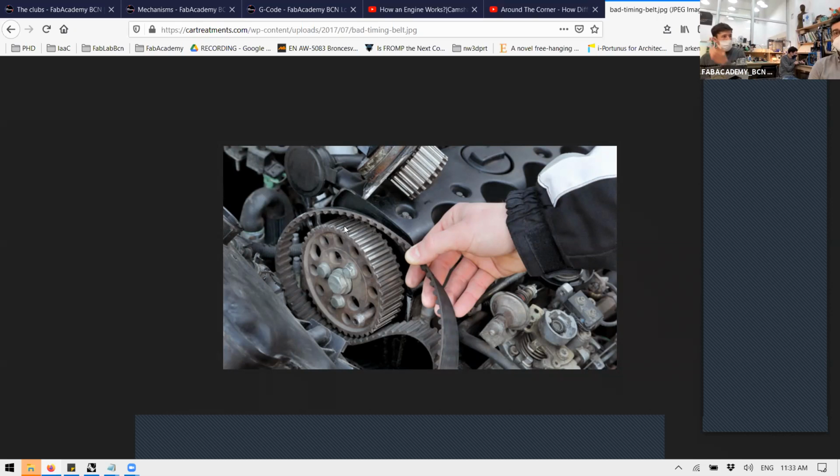Yeah, there are different sizes and they have standard GT2, GT6, GT8, GT12, GT20. Depends on the weight, the amount of load that they can carry. So, for example, these ones are quite easy to determine. If you need to pull 20 kilos, you need a belt that holds at least like 20% more. So you dimension based on that.